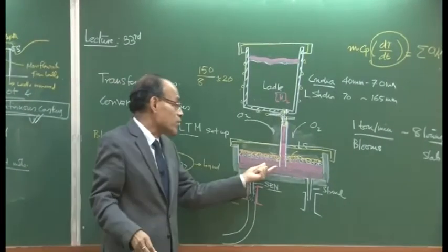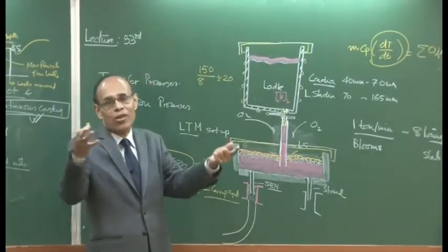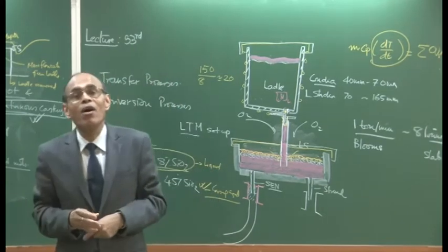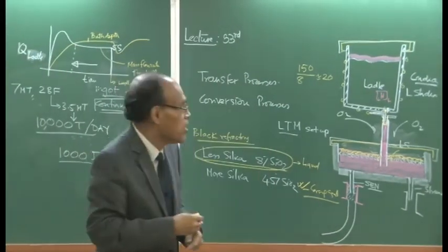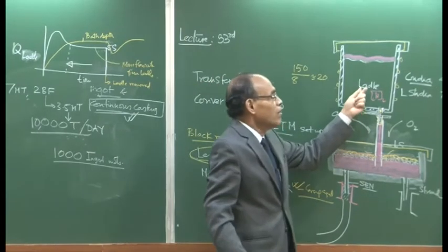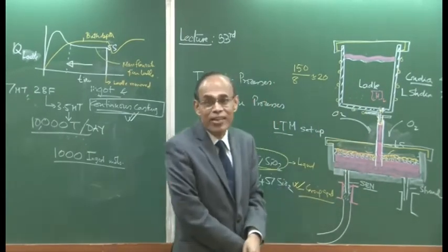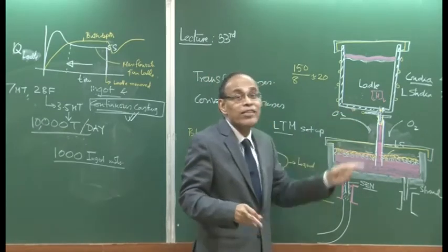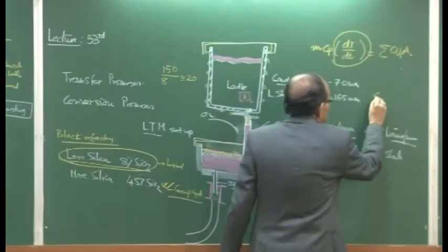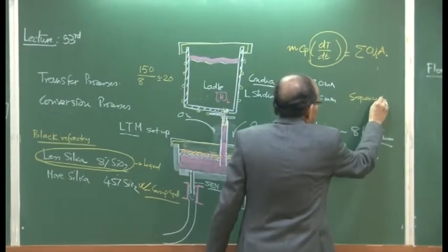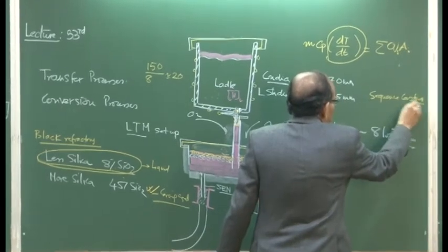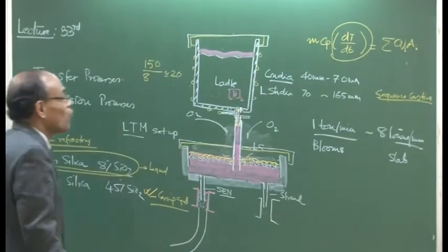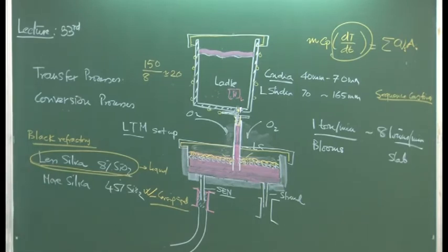On the other hand, if you are making a huge volume, because your customer has come to you and said that I require 5,000 tons of a given grade of carbon steel, obviously you will not have one single ladle, you will have maybe 25 ladles. If you cast one after another ladle, that is called in the industry a sequence casting operation, the same grade of steel being cast continuously. When the volume requirement is small, you have only one heat, single heat casting, as opposed to sequence casting.